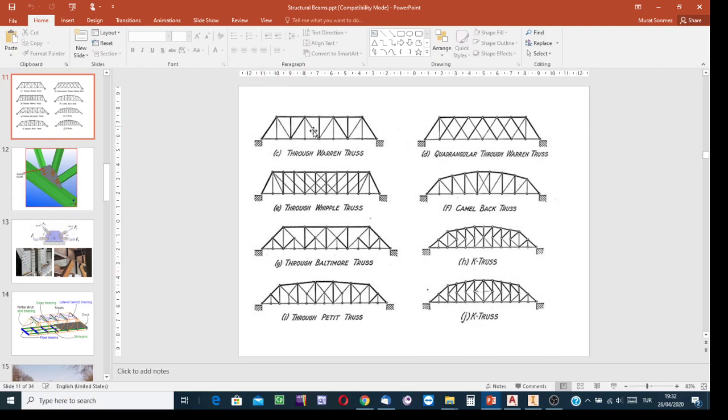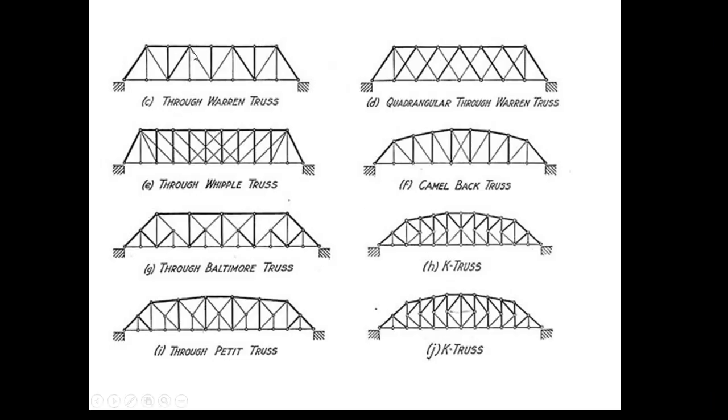The lines, yes, for instance here, a Warren type truss, similar to the figures that can be found in statics books, strength of materials books. Okay, it has been schematically shown. These schematically shown lines correspond to each of the members, structural elements. But say at the first stage, draw the necessary sketch, I mean draw the lines, okay, considering that a line is passing through all the center points along all the cross sections throughout the member, throughout the element.